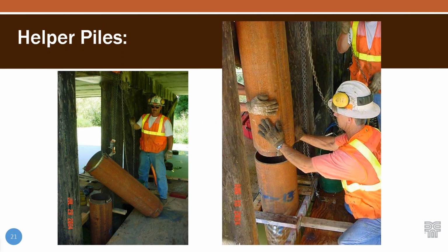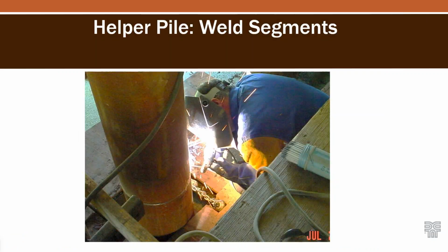The other item with this that I would highlight is that you're going to have to splice. You're going to probably have to splice at least a few times as you do this because you want to get that new helper pile buried as deep as you can into the ground to get your resistance and then also to keep it from washing out or scouring under. And so you get some welding in practice. And so here they are making a welded splice as they jack that first segment on the left there down far enough they're not shimming anymore. They say, okay, let's splice it and then we'll start the process over again.